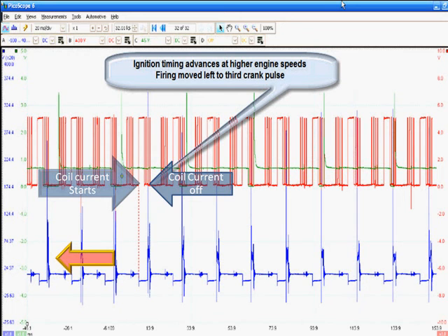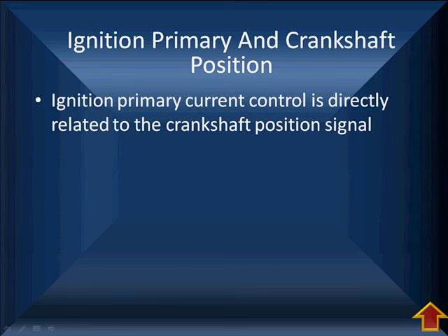We have an entire section on that later, but I cannot pass up the opportunity to say, when you look at this, take it up off idle and see what it looks like off idle, where the coil has to saturate faster and work a little harder. The plugs work a little harder. The mixture is going in and out of the cylinders a little faster and has more demands on the delivery of the fuel off idle.